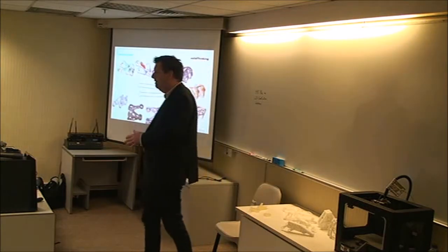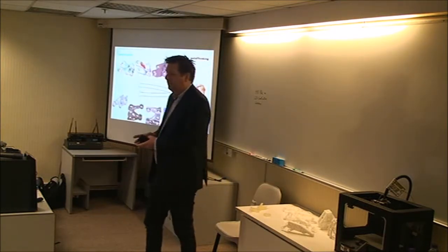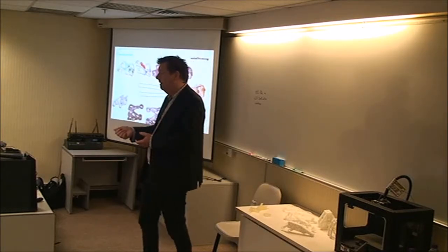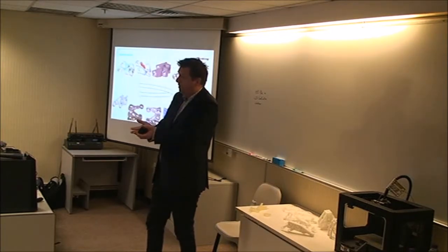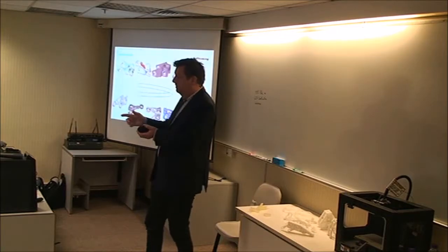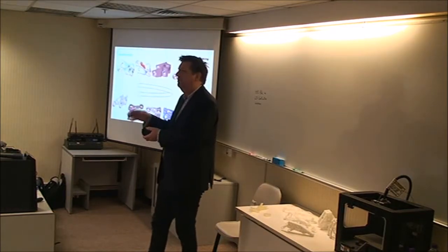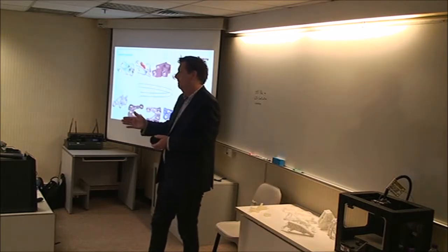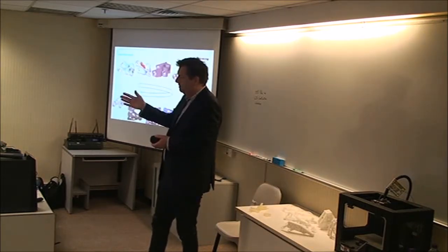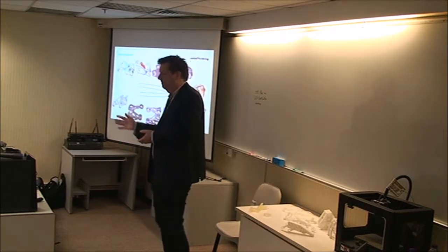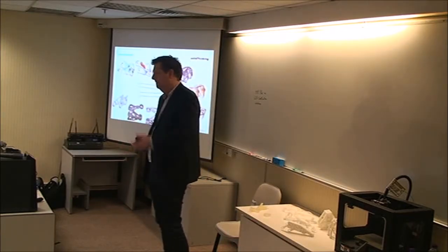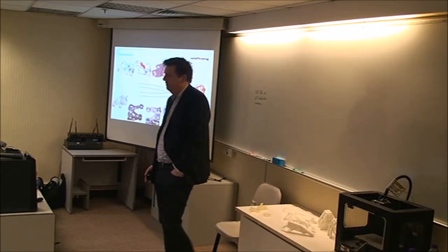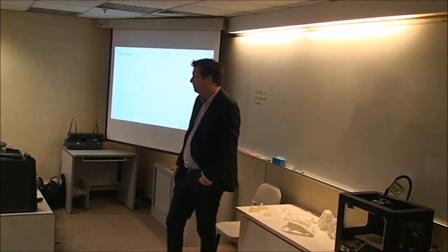It's like every stage. The very first one, you get your existing design, you confirm it works. If you don't know your loads, but you've got a part that you know works, you can just put unit loads on, measure those responses and use those as your target for your optimized design. That's what a lot of customers do. Existing design, package space, optimized design, print, pre-processing, finally print. So we need more spaces in our circle of life printing stuff.